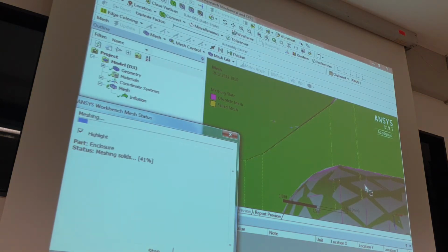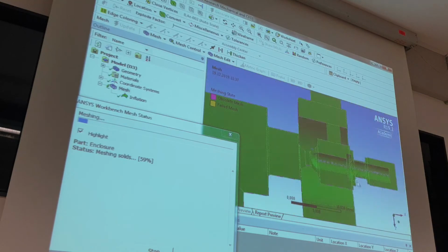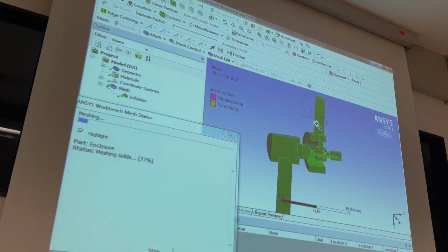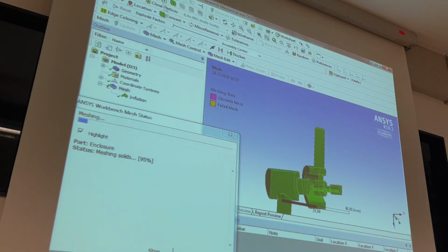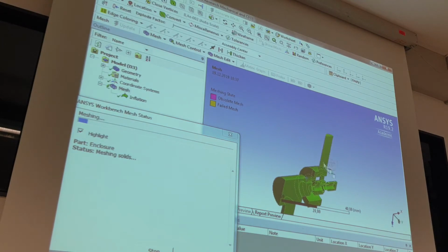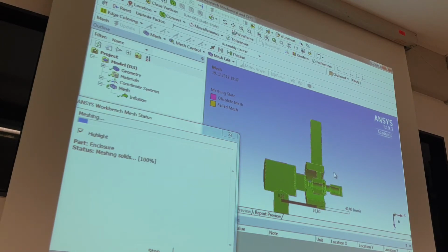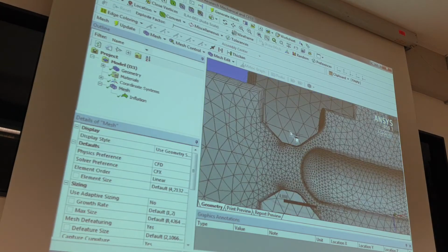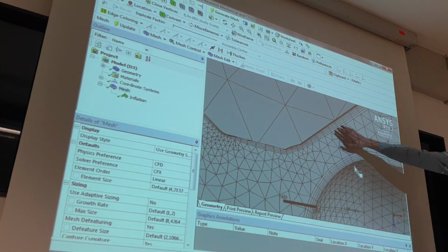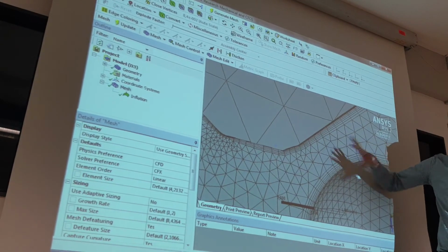Of course, we can say, for example, separately, here were too many elements, we can refine here, not so fine. Okay, we have to do something, but the main target to get good results is to have 5 element inflation and 2 elements between. So now it's very good.